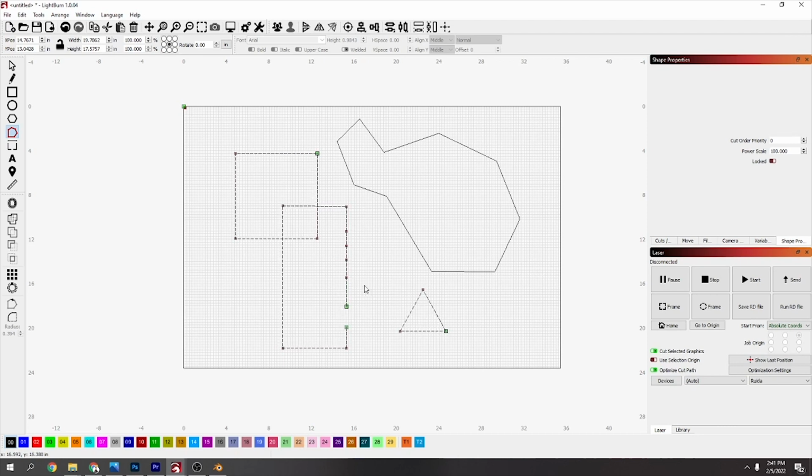And with this, I mean, you can do a lot with these. Now you can move these around. You can press S to smooth them out. If you press L, it'll change it back to a line again. So now it's not smoothed out anymore.